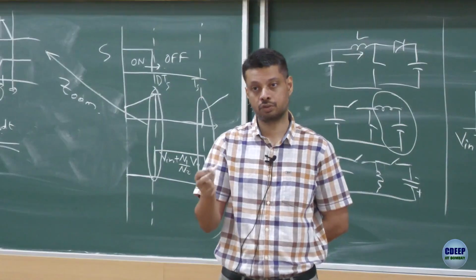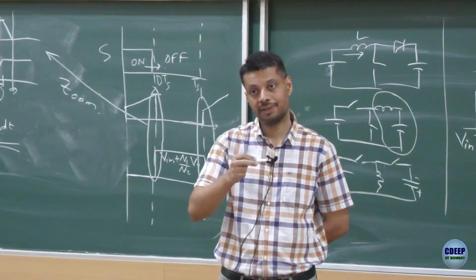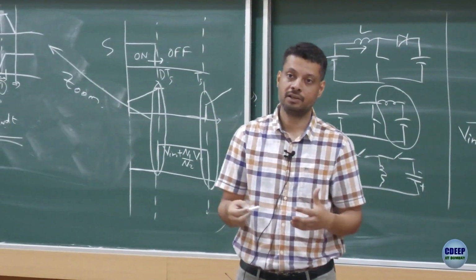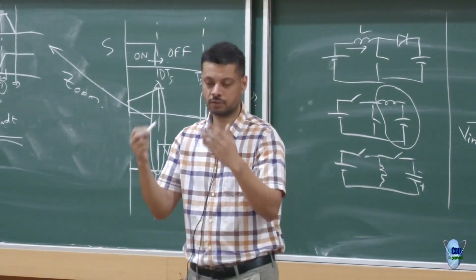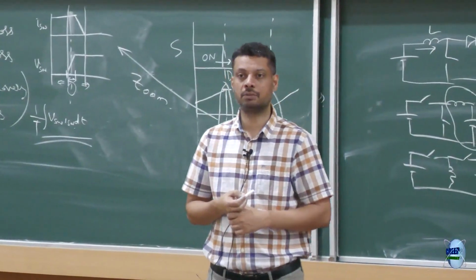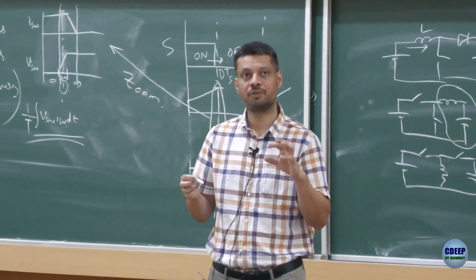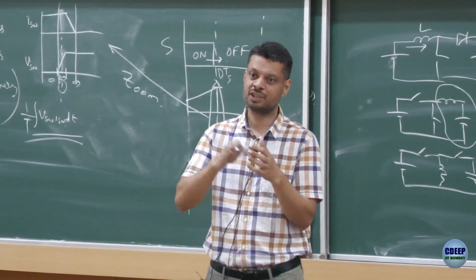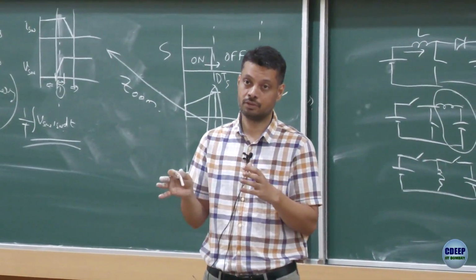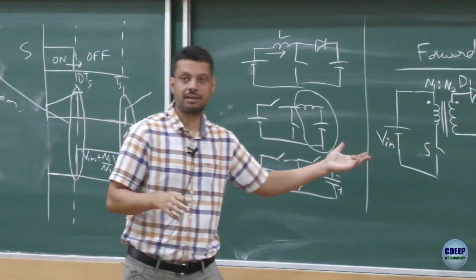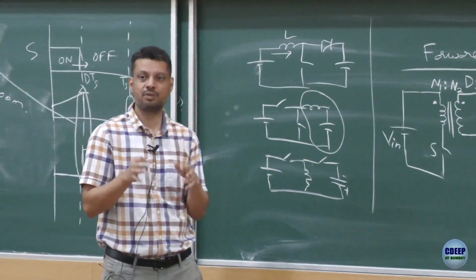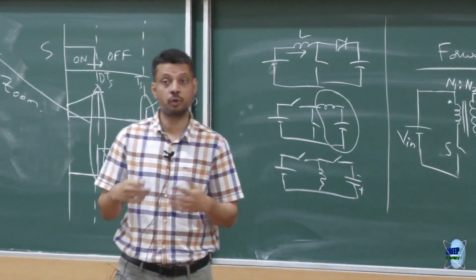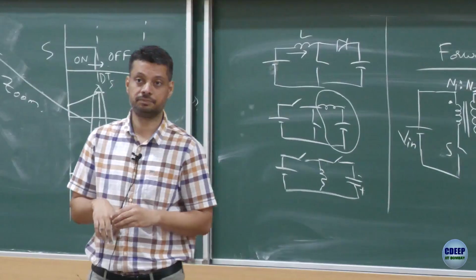If you use a buck boost, practically all 350 volt energy is dumped into the inductor and then transferred to 400. Of course you need to derive a detailed equation, but broadly speaking, 350 to 400 would come out more efficient using a simple boost than a buck boost. So same thing here: instead of using a buck boost, using a dedicated buck or a dedicated boost has more potential of giving you better efficiency.